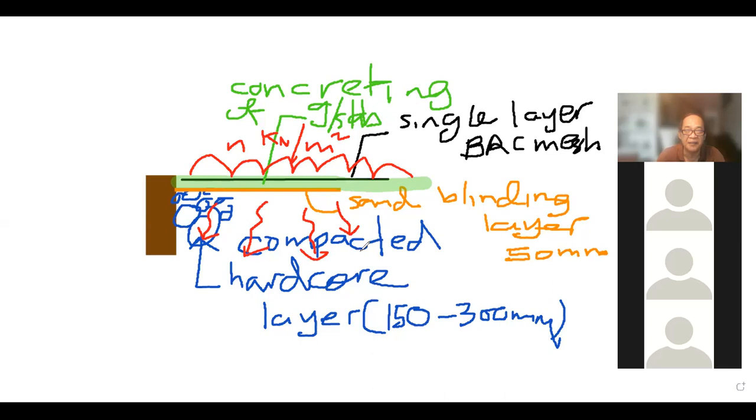So for non-suspended ground slab, we need to have good soil, meaning that when the load is transferred to the soil, it would not settle. Because if the soil starts to settle, then the ground slab will also start to settle. Because there is no physical link between the concrete ground beam and the concrete ground slab. There is no physical reinforcement connecting the ground beams with the ground slab. So these are two separate entities.